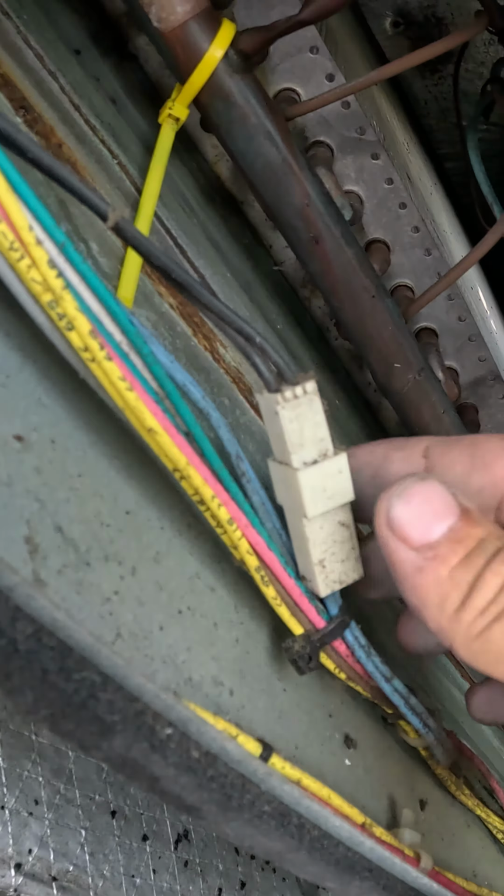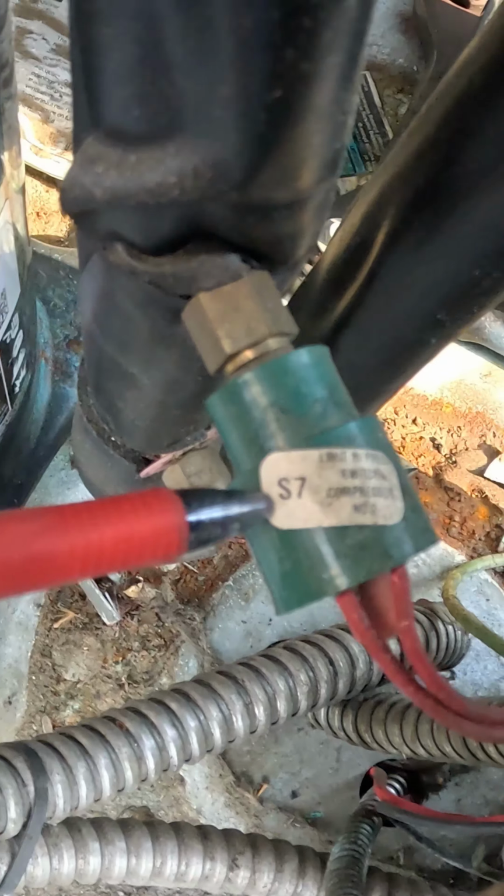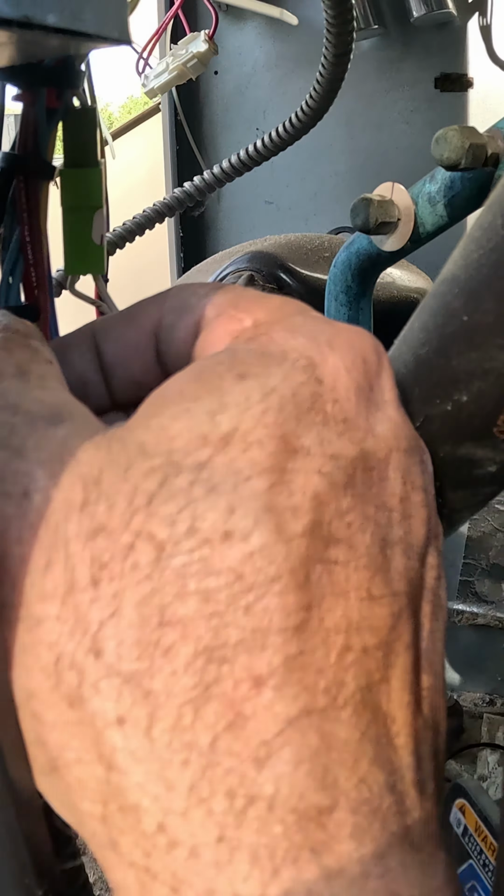Come over here to S7, it's going to be the high limit switch for compressor number 2. So here's compressor number 2, and we see an S7 right there. And those wires are coming over here and connecting to these 2 blue wires. We cut that zip tie for educational purposes. Alright, so this one side says S50 to S7, and this side says S8 to S7. I'm starting to get all my numbers confused.